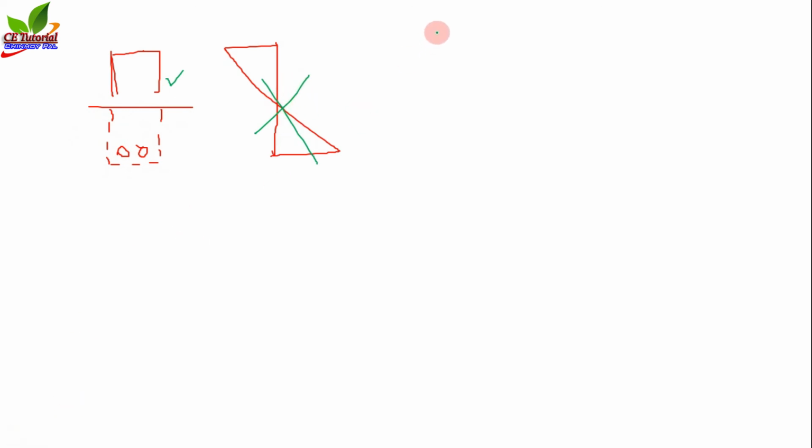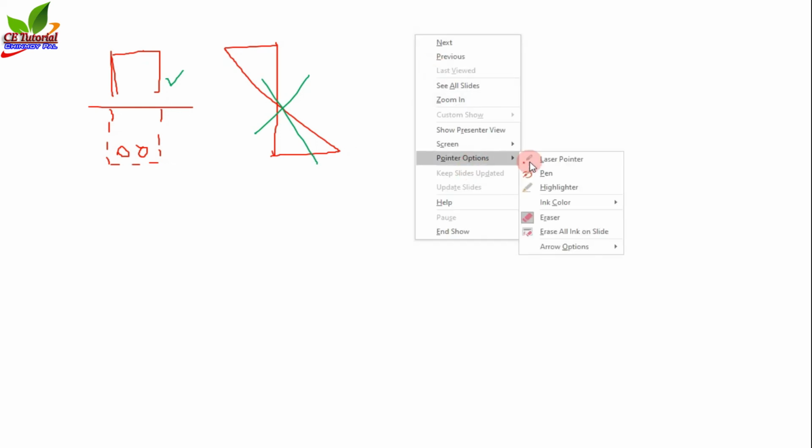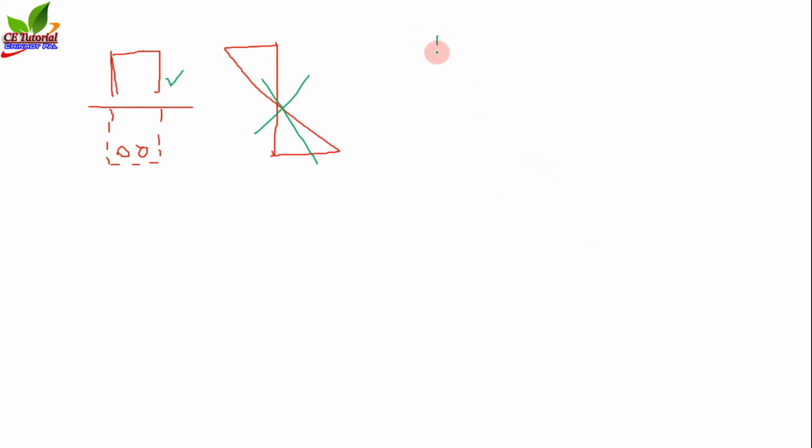So what is the correct bending stress diagram? The correct bending stress diagram should be this. Above the neutral axis, we have nothing to neglect. That's because that is pure concrete. So we can directly draw the bending stress diagram, that is a triangular one above the neutral axis, no problem.